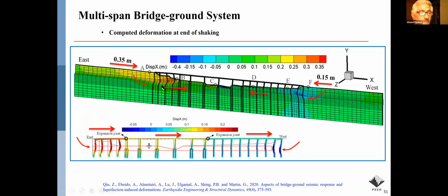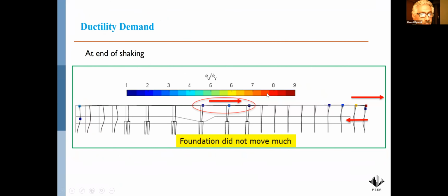deformation of the slope. And since time is tight, maybe I can use this slide here and mention to you that on this side there is deformation of the slope. On this side, there is deformation of the slope from the middle here, the base, but there is also, because the bridge moves towards the right side, a double action here on the piles, and this motion here is a consequence of the motion on the left side.